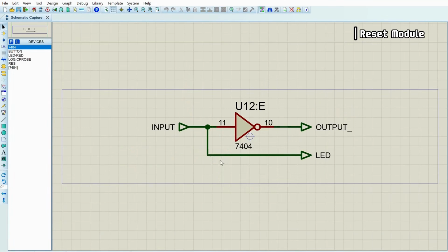Here is our internal circuit. When input enters as a 1, the output becomes 0 and the LED lights up. As our project ran on a common anode method, the output became 0 as soon as the circuit activated. The whole game reset and a new game started.